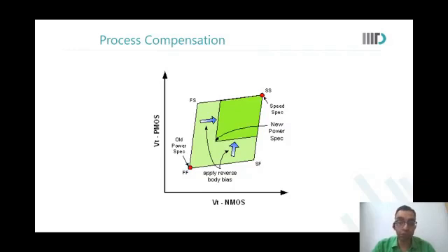But on fast, we also know that the leakage is very high and the delays are much lesser. So you signed off, you designed something to operate at 2 gigahertz. Now a die is manufactured or a lot is manufactured which is operating at 3 gigahertz. Now overall ecosystem, आपको पता है 3 gigahertz, you cannot really operate the system at 3 gigahertz because there could be resonance issues, there could be inductive effects which would come into picture and so on. So you anyway want to operate the particular die at 2 gigahertz.